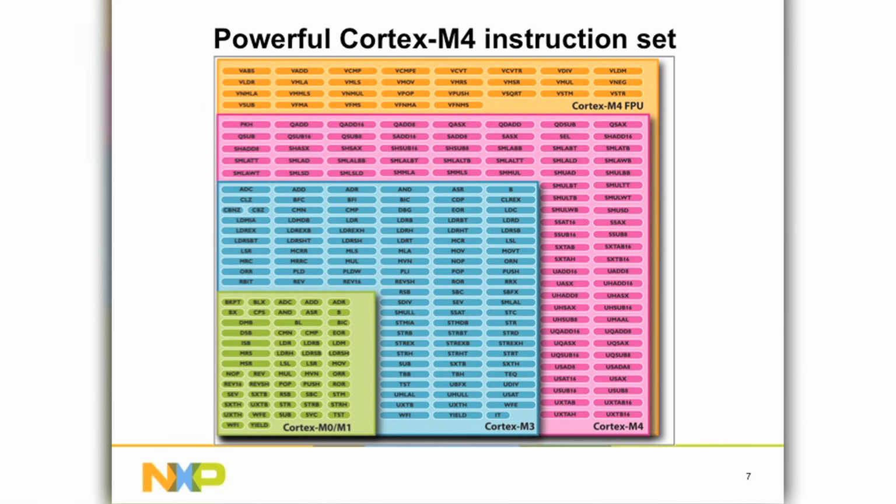You're probably writing in C code, so it probably doesn't matter anyway. You'll recompile it, but if you do try to optimize libraries, it's nice to know that the libraries are compatible. Is there a lot of pipelining for instructions? There are only 3 levels of pipelining in the M family, so it's not a tremendous amount of pipelining. Obviously, that's one way DSPs go faster, if they really stretch out the pipelining, and then, of course, when you have an interrupt, you have to flush all that out. So for now, I think it's 3 levels of pipelining, and in the M4, some predictive calculations.